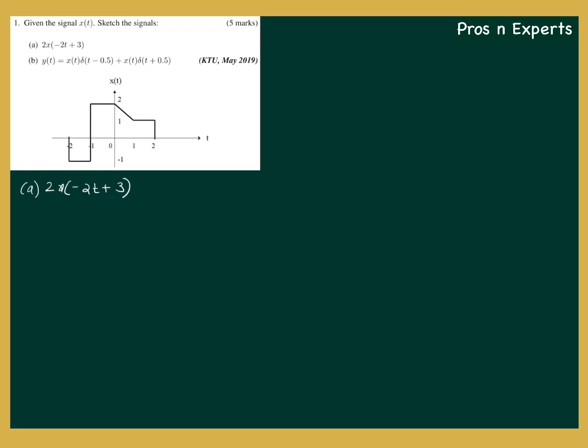From the question it is very clear that there are two signal operations. The first one is shifting by 3 units and the second one is scaling by minus 2 units. We know that if a signal operation consists of both shifting and scaling, the precedence rule tells us that first you perform shifting. First shifting should be performed, then scaling.